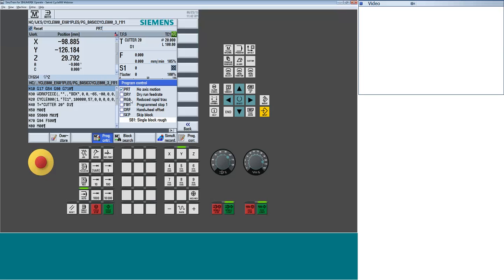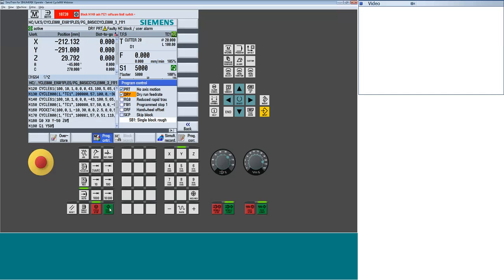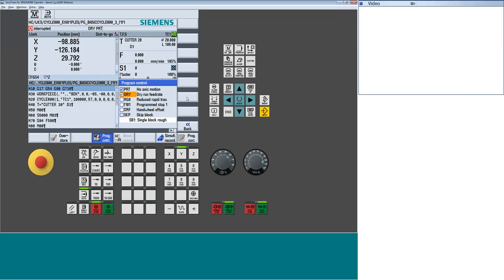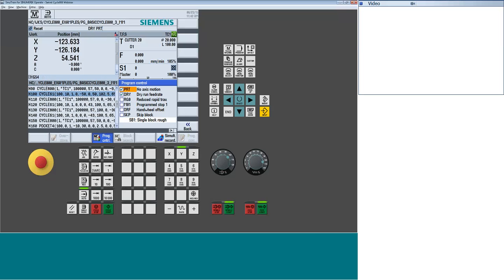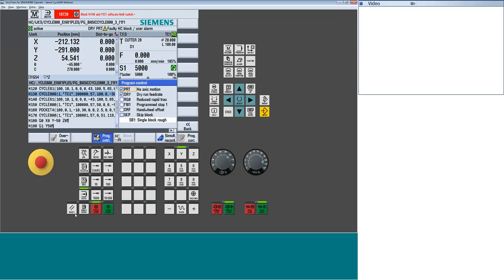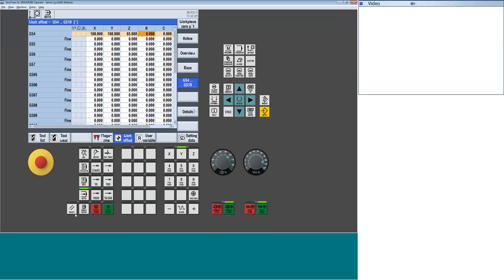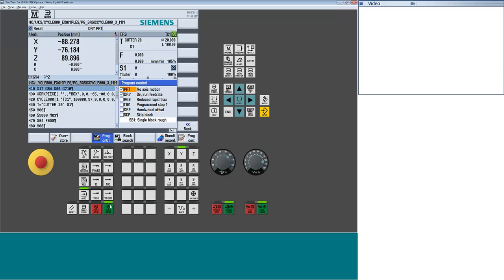Now, the other thing is I certainly don't like to waste a lot of time. If it's a long cycle time, I don't want to run this real time. So then I'll leverage the dry run mode with the program test mode. Cycle start, it's going to run at a much higher rate of speed. Over travel, I now can start to go in and maybe adjust where she is in space. Maybe I was able to drop the Z a little bit from a fixturing standpoint, whatever. And now I can see I still have a little bit of a problem. So maybe I would need to move the location of my fixturing a little bit, and then keep rerunning the test until we can get all the way through the scenario.